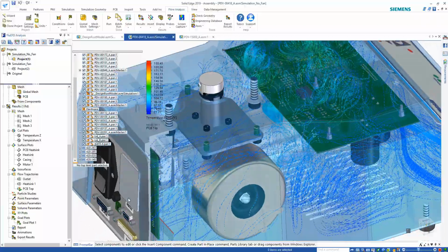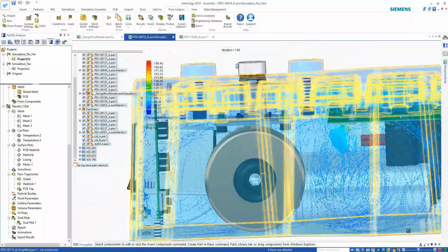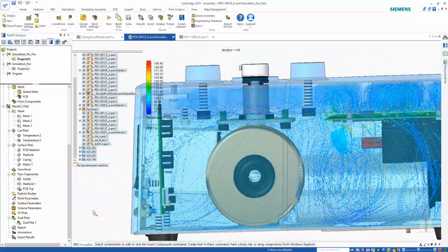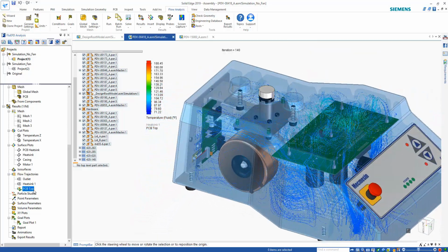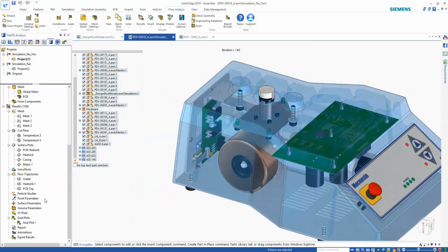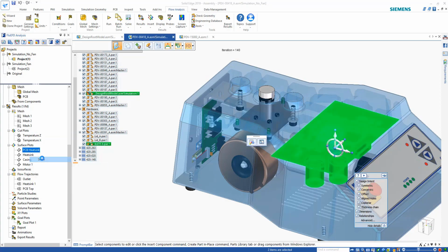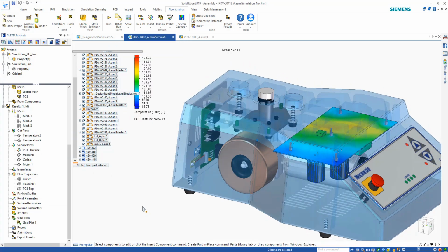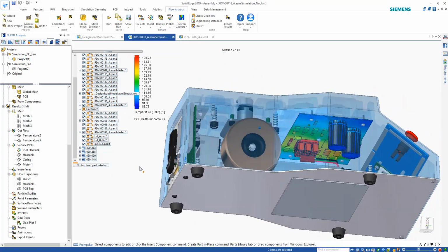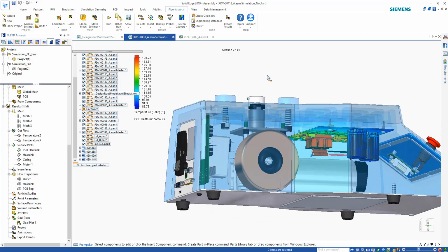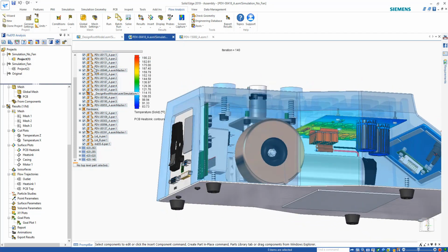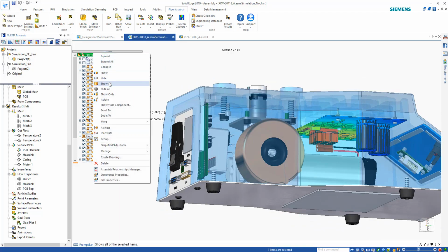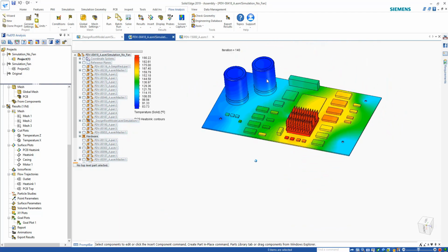If we show the flow coming from the top of the PCB, we can again see lots of internal recirculating flow, especially above the hot component. Some flow can be seen leaving the rear vent, as this is physically higher than the lower vent. The board temperature can again be visualized in the subassembly context. A maximum of around 190 F can be seen around the CPU, with the heatsink being red also.